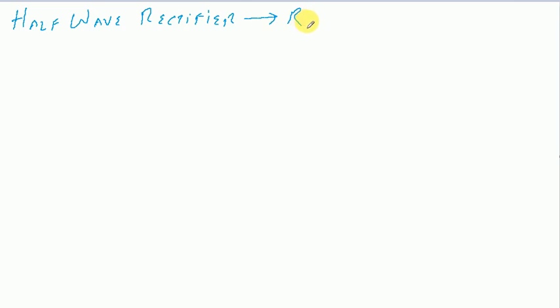In this case, we'll consider a half-wave rectifier circuit with an RL type of load, commonly referred to as resistive inductive load, or simply the inductive load, because any inductance will have some internal resistance, even if it doesn't have any external resistance. Basically, this type of load is more practical in certain industrial applications where we have different types of motors and other machines serving as load to various types of sources.